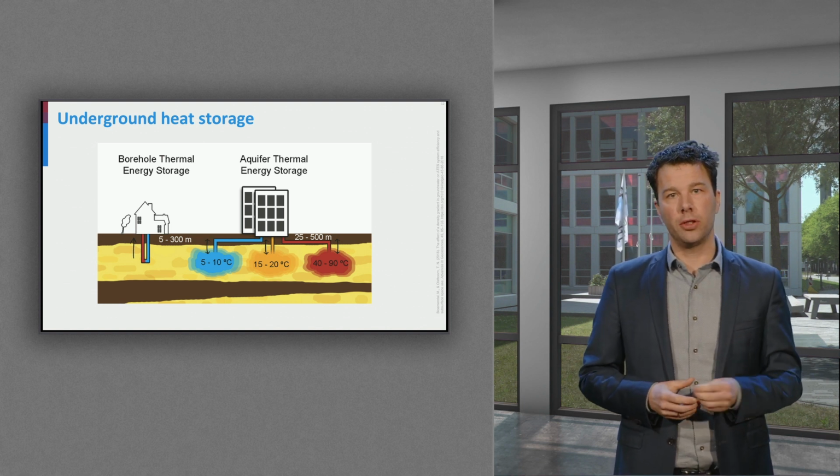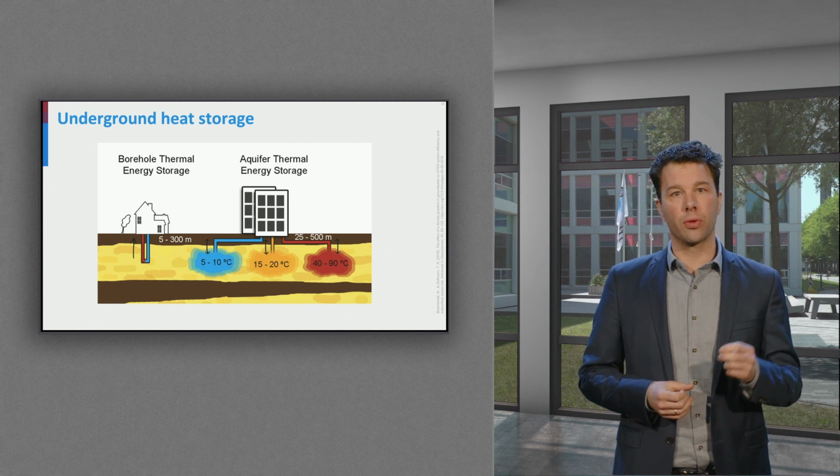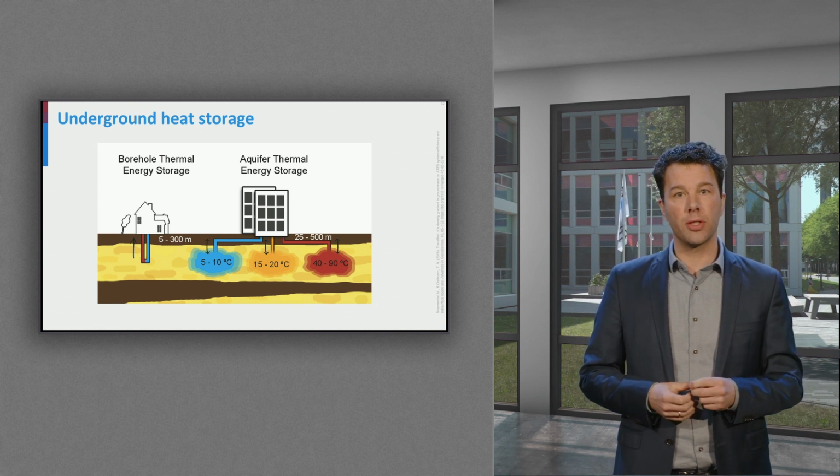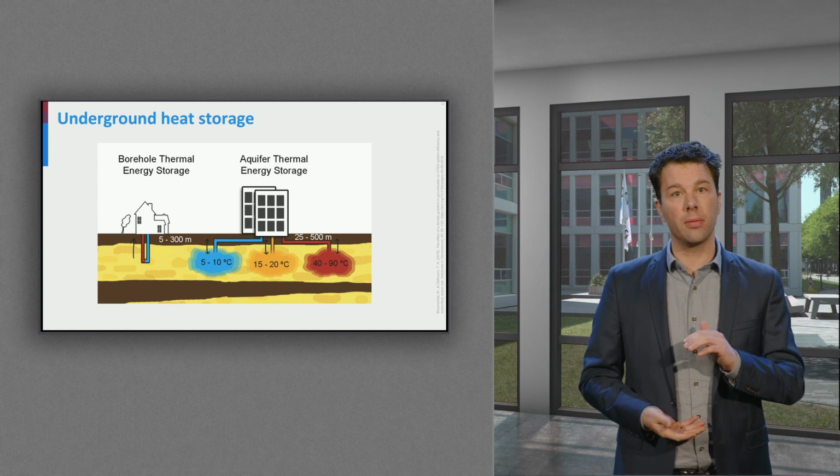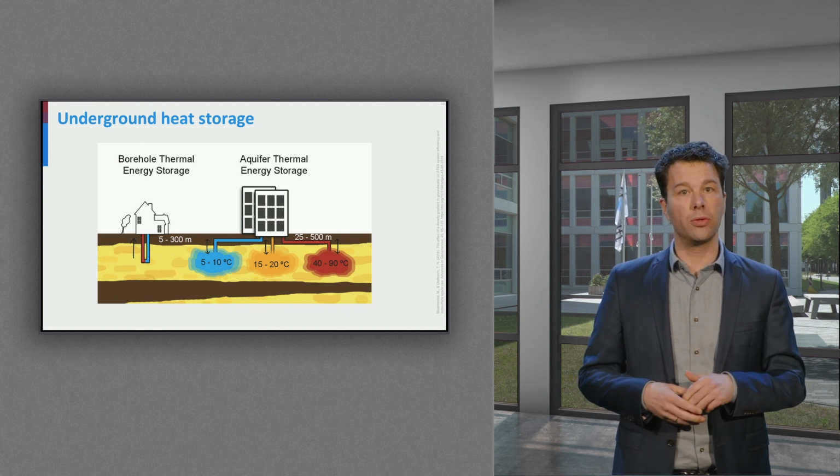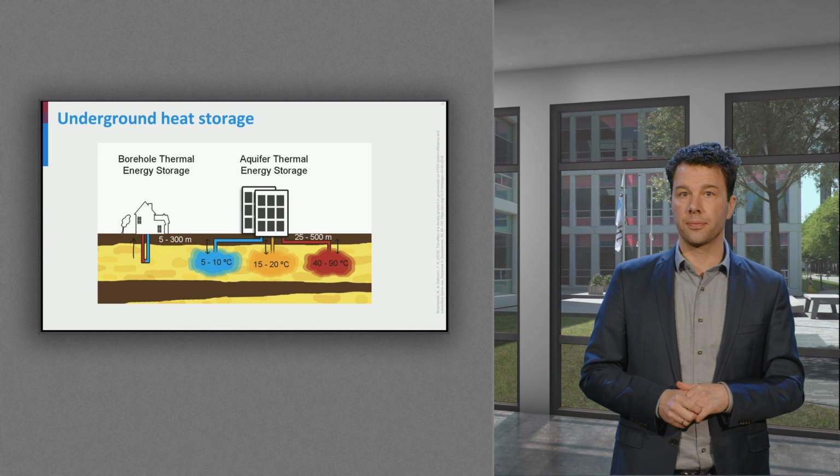The big advantage of also using borehole heat exchangers for cooling or adding heat to the system in summer is that their length can be designed much shorter compared to if you were to only extract heat from it.